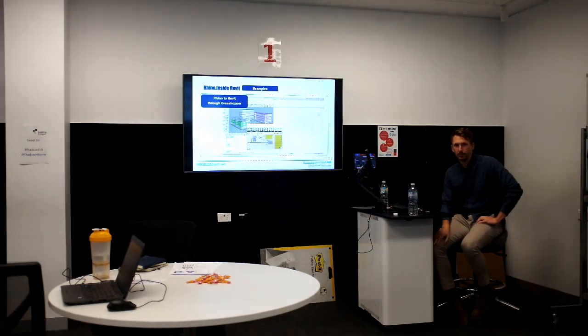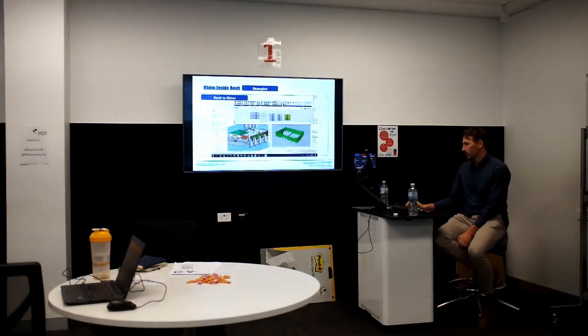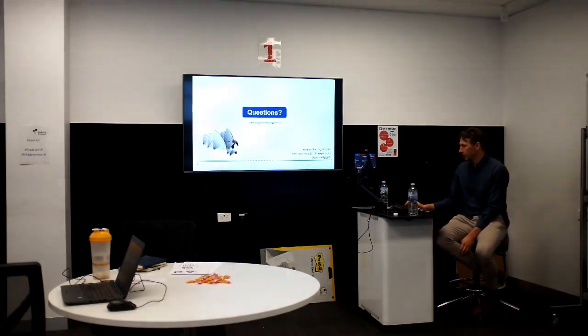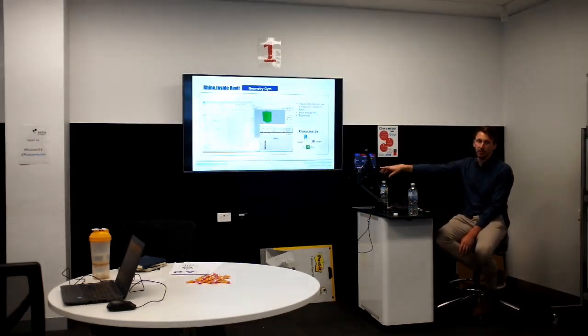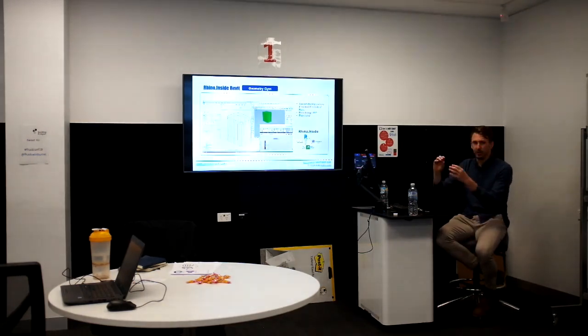Can Geometry Gym keep the connection alive? So the way Geometry Gym does it is through IFC elements. Once you bake that geometry to Revit, that's a Revit element, and it's got an IFC GUID on it. Then you can close Grasshopper and keep working in the Revit model.